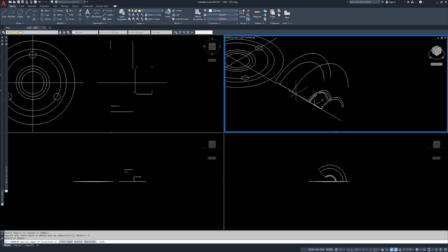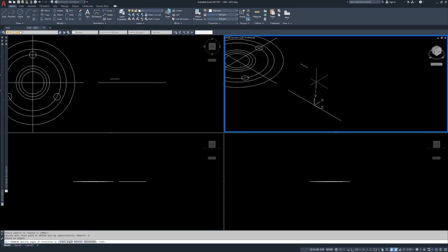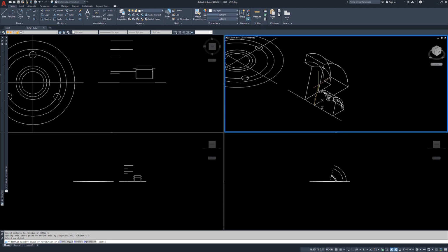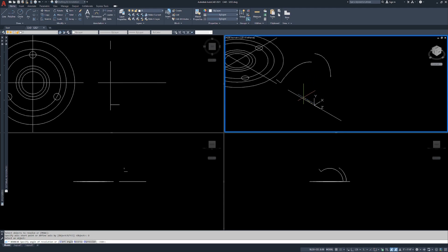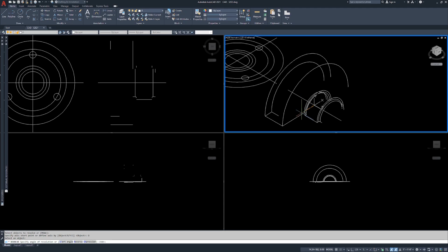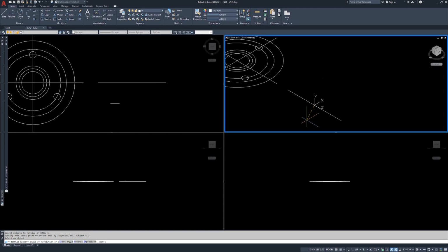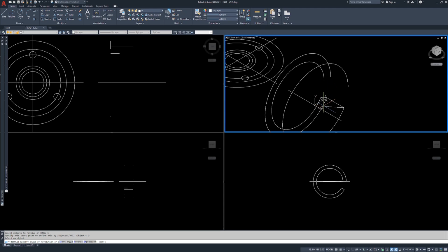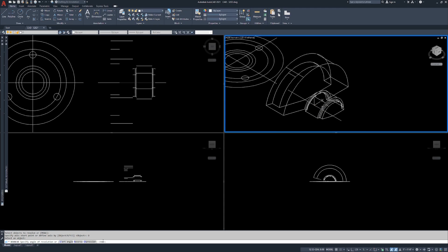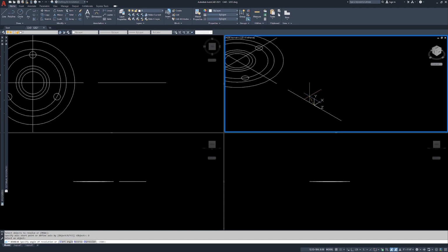And when you single left click it, look what's happening in the upper right hand viewport. As we rotate the mouse cursor around, it's actually revolving the entire part. So now in this case, because our part is closed, we don't want to be a little bit short. We want to use 360. 360 defaults for the revolve command. It automatically defaults to 360 degrees, which is a closed circle. So in this case, we're just going to hit enter.